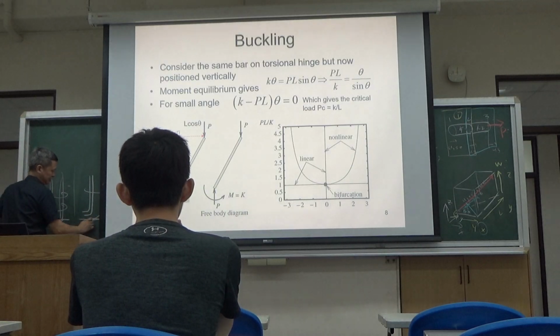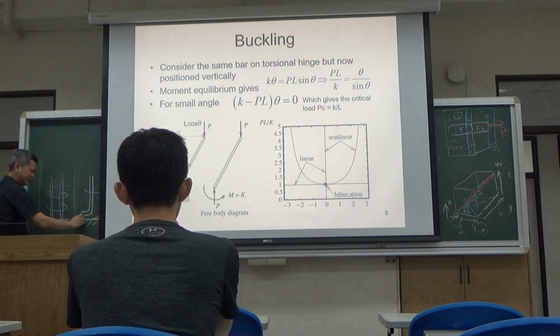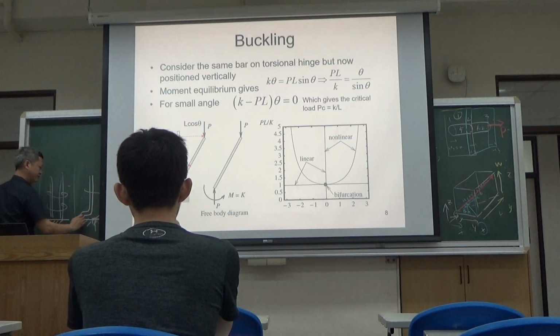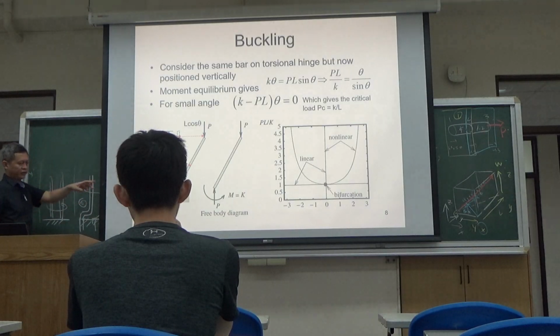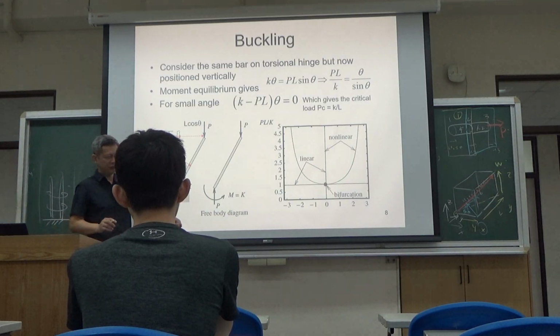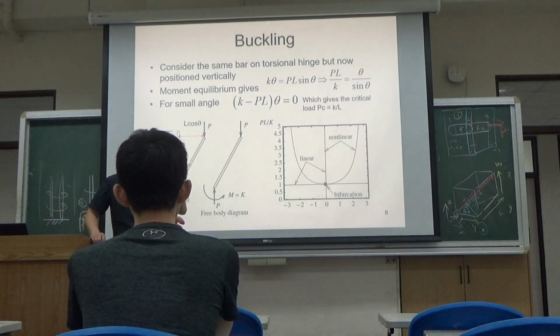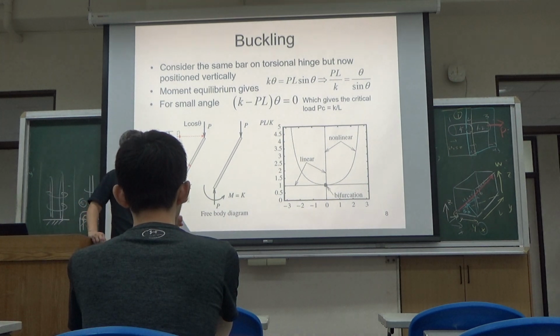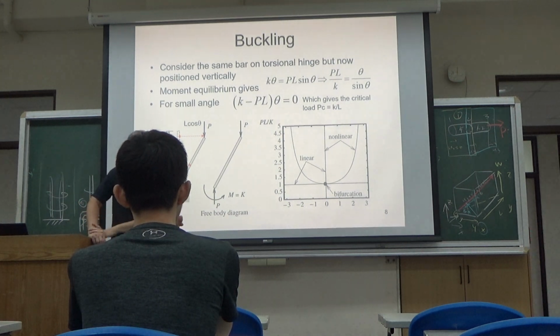understanding on the mechanics. It may start from the same vertical position. If you bend, this is equivalent to a torsional spring. Or in short, this is a hinge. A structure is a structure when there is no hinge. When there is hinge development, this becomes a mechanism.